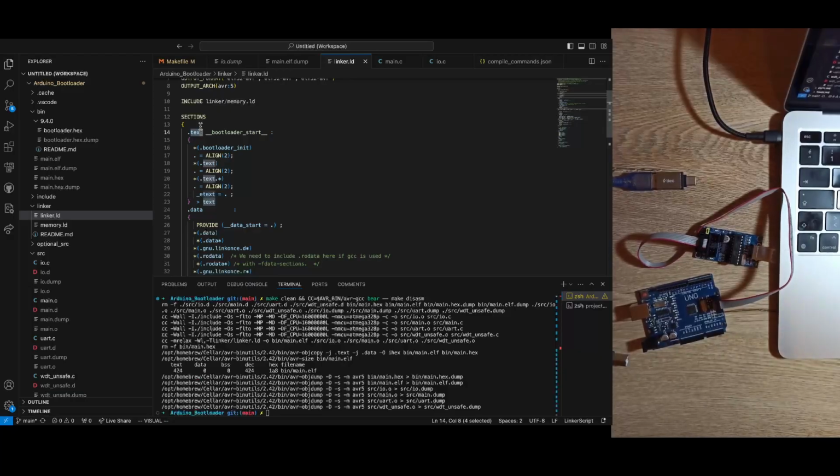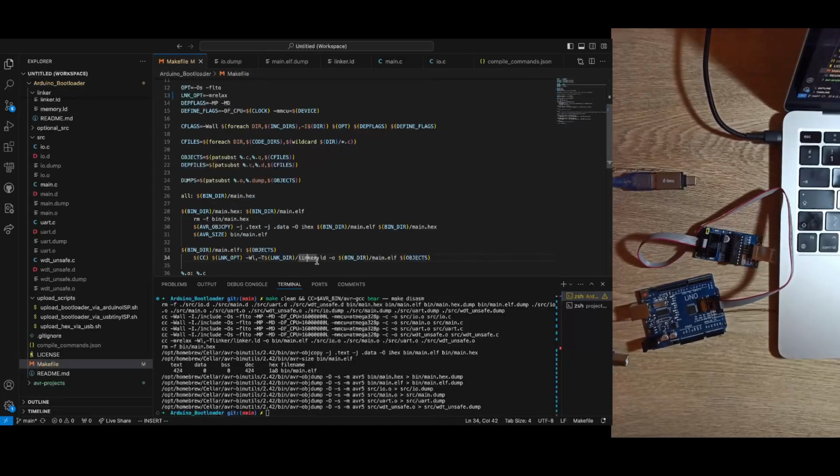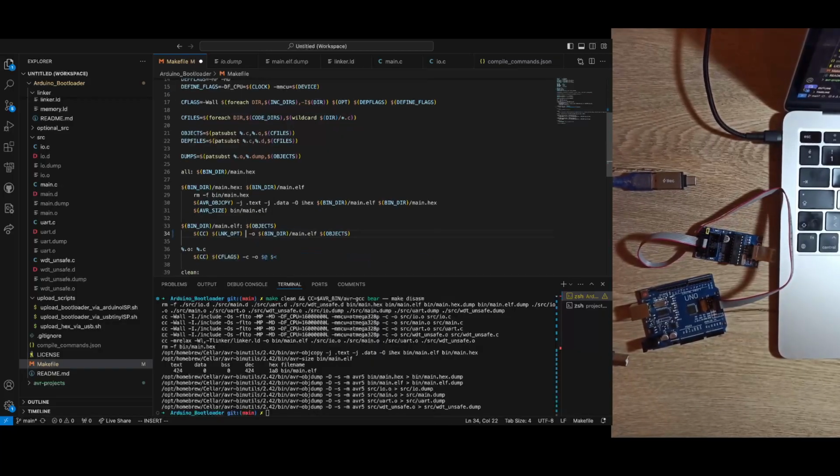If I use that default linker script, my program is linked with those standard object files that come from the library, and they're going to inflate my program size. I don't need them, and it's going to affect my program correctness too.